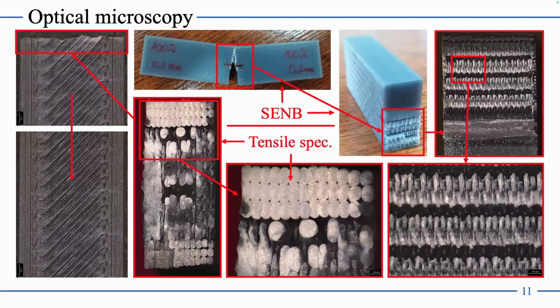So PLA, well, in literature findings, there's a lot of statement that PLA is actually a brittle material, which, if you see the tensile specimen images of the fracture surfaces, we see that the fracture surface is fairly brittle.